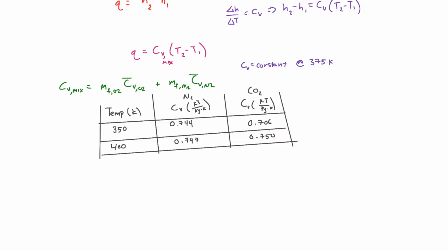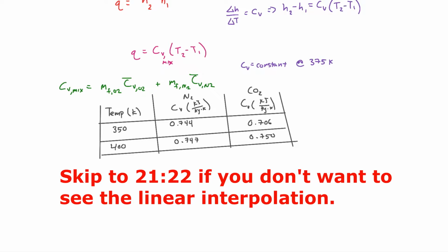And the same goes for CO2, although it's more of a drastic difference, but it's still roughly 0.725. It's nothing too insanely different that will make your answer different from the textbook or from the final answer on an exam. If you're under a time constraint, just estimate the value from the text table.